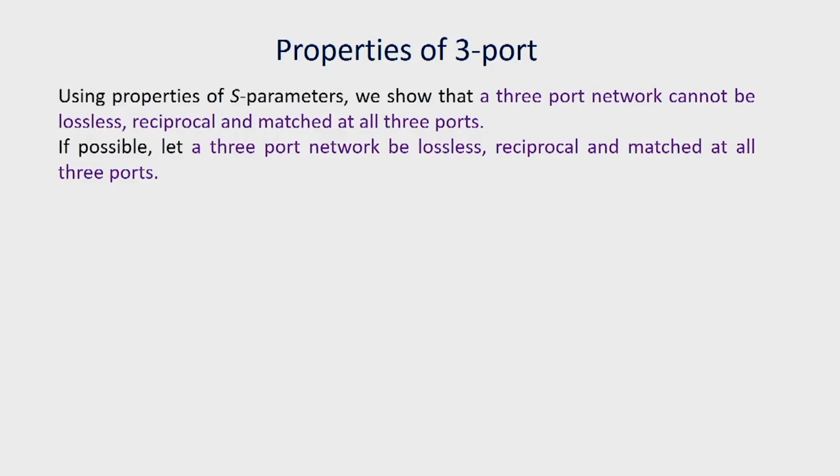In order to prove this, we start with the assumption that it is possible to have a 3-port network which is lossless, reciprocal and matched at all 3 ports, and then we will show that such an assumption will essentially lead to a contradiction.